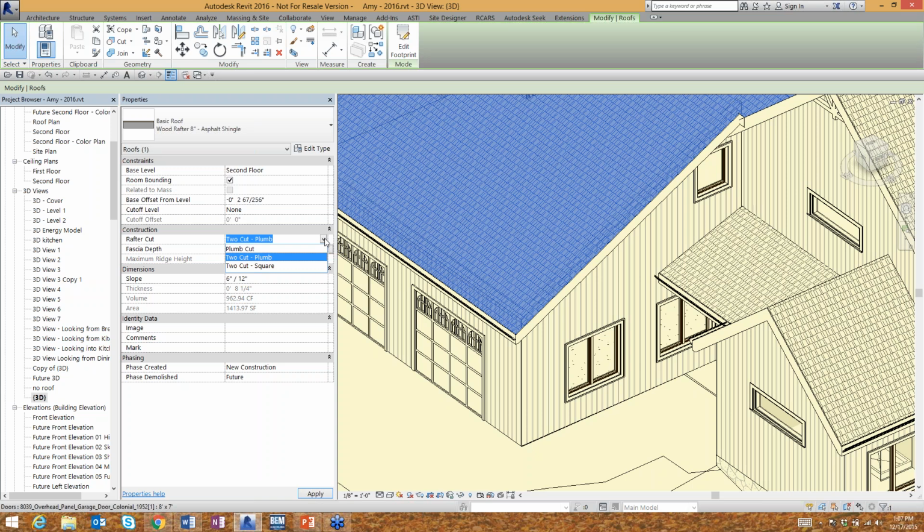Okay, well, another question that we can address as well, it's quite simple, is would you discourage linking 2D CAD details into a Revit file? Not at all. I think that's perfectly fine. Revit's got the ability to bring in those 2D files, and for sure, if you got them already drawn in AutoCAD, by all means, there's no reason why you shouldn't reuse them and take advantage of them inside of Revit.